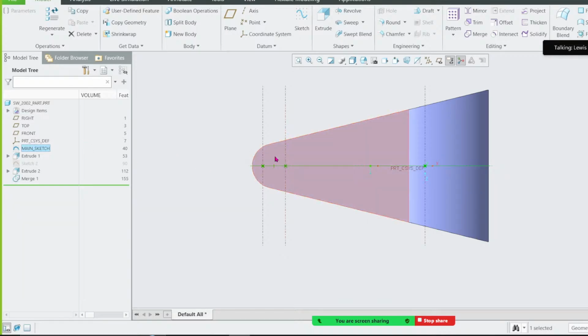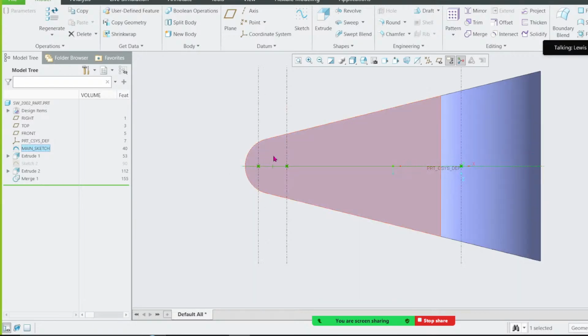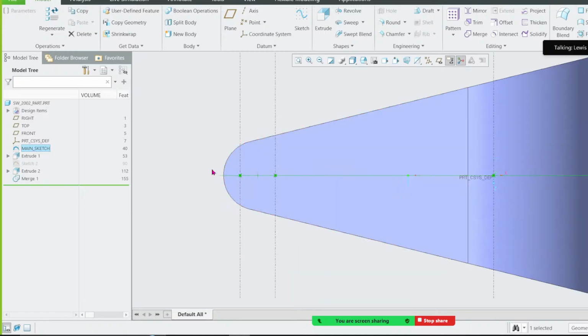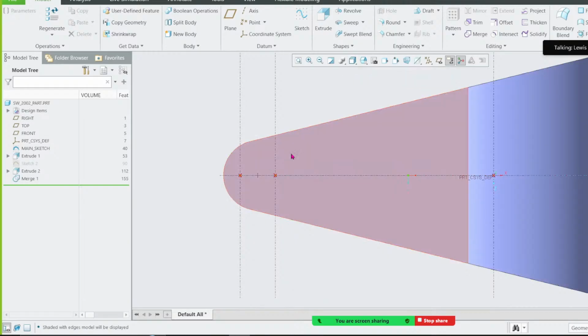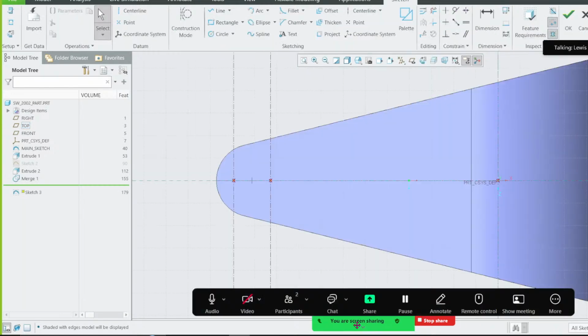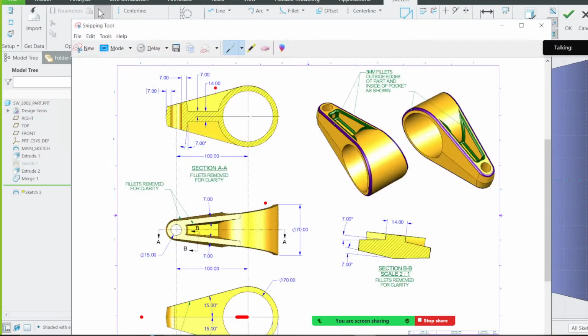Now, remember the hole that was here. I said avoid putting the hole inside. Because sometimes if you're designing a component that is going to be manufactured by injection molding, especially plastic design, you want to put a draft in that hole. When you bury that hole inside the feature, it will be very difficult to put a draft. Therefore, I have these 2 points that are very important. And if you want to move anything, let me first of all sketch that hole. This one here.